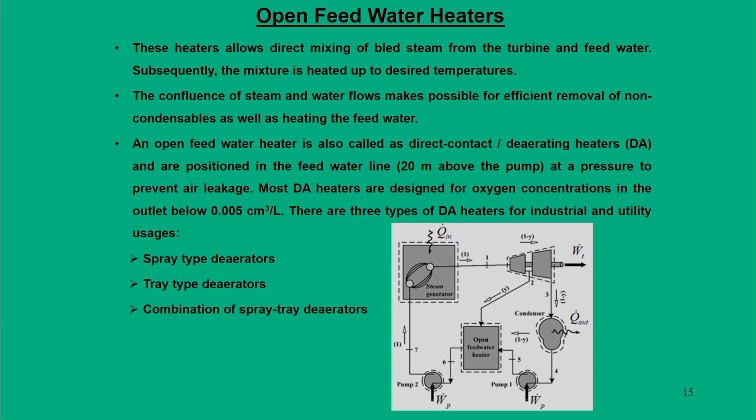Then moving further, the other concept is the open type of feed water heater. What we have discussed so far is that open feed water systems allow both the steam and water to be mixed together, but then the problem arises that the steam may be high quality steam, but the water may have a lot of impurities. So, when they mix together, there is gas formation, there may be the possibility of oxygen concentrations, there could be non condensable gases.